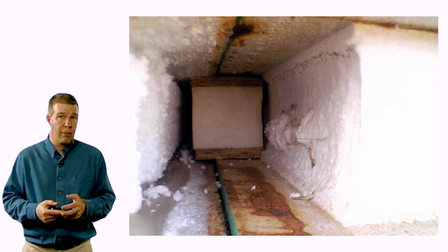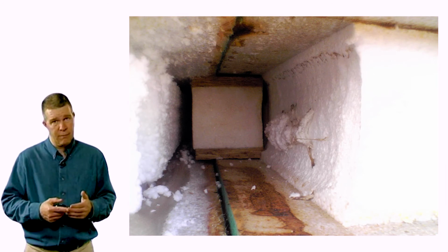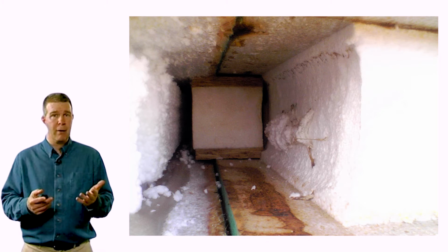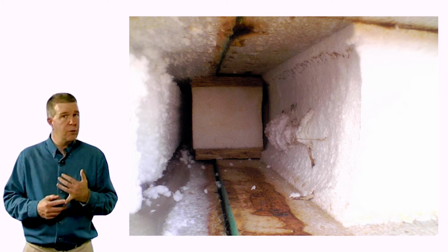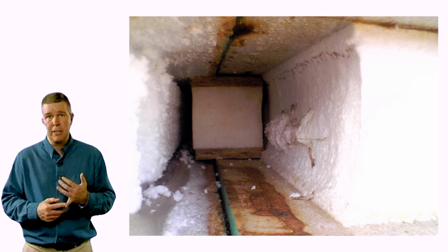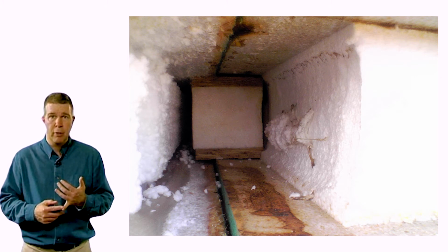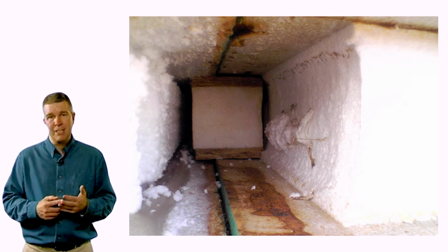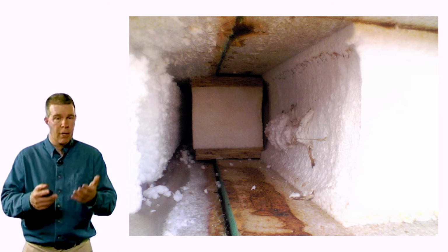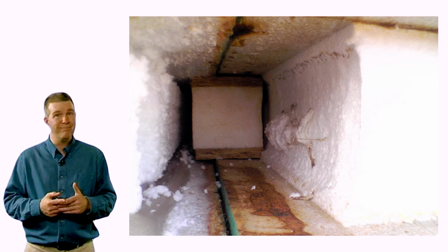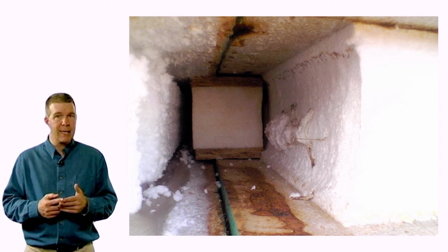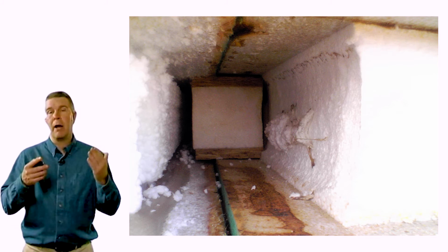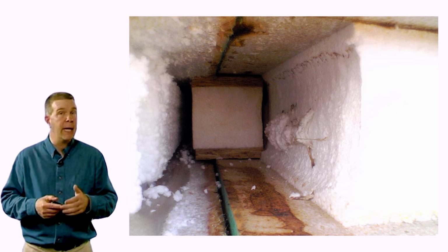Now when we talk about thermal voids, this is the worst case of a thermal void. This is a SIP panel that's being put together with a block spline, and the installer didn't do a very good job at determining how tight this spline should go into this joint. Look at the amount of air movement that potentially we have going around this spline. You've got a perfectly good system poorly installed, which doesn't make it work. The mastic that you see in the joint isn't sealing anything to anything, and you've got a huge ability for air to move through that system. In anybody's book, this is a bad install.